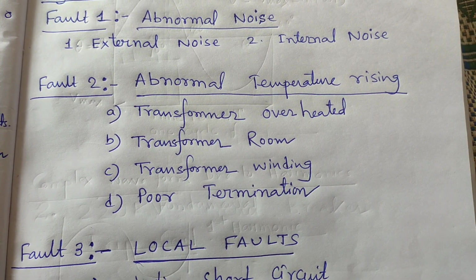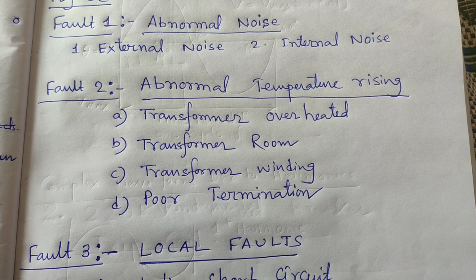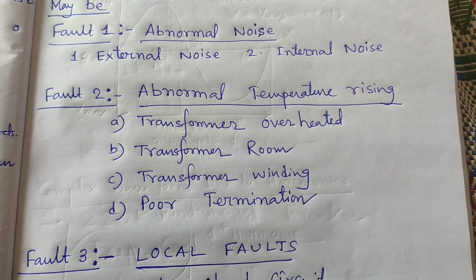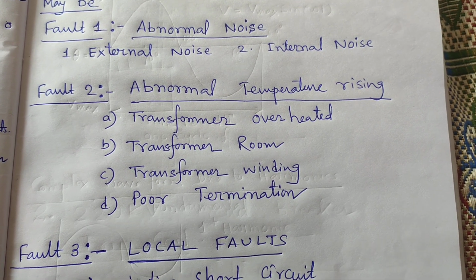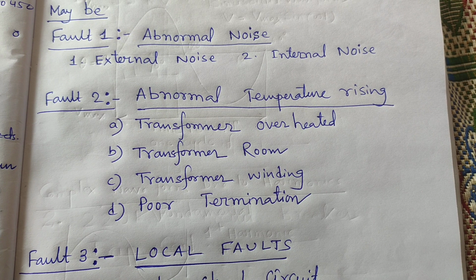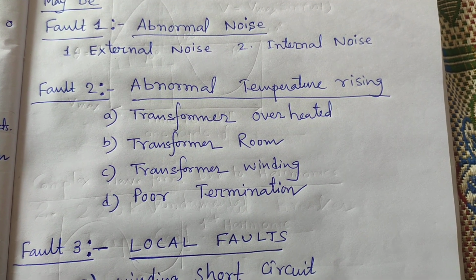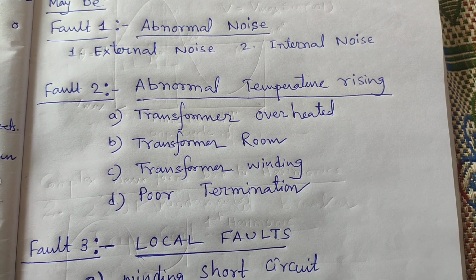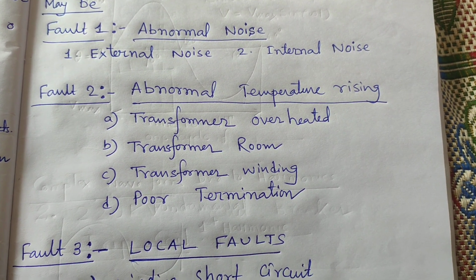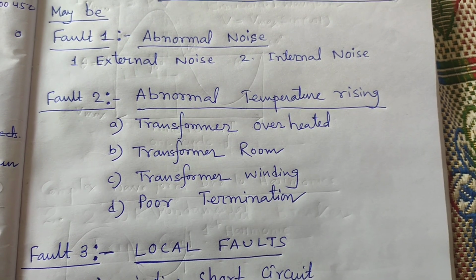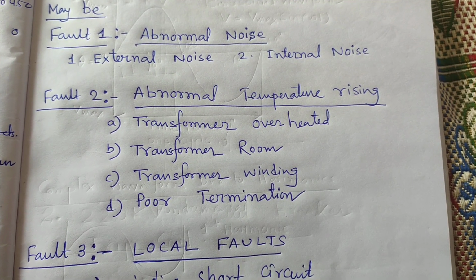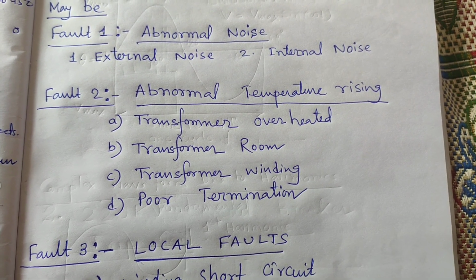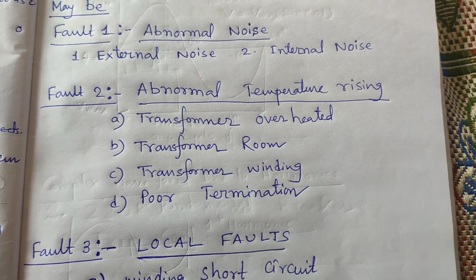Transformer winding temperature: the diploma engineer or the operator posted at the transformer observes and takes the data from the transformer marshalling box, to see whether the winding temperature and the oil temperature are under control or beyond the range. So we should check that winding temperature. If the winding temperature is haphazardly increasing and decreasing, we should inform the testing department for testing of the transformer and take their recommendation on what should be done in this situation.